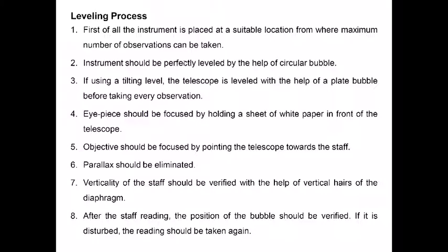Once that is done, you will use the eyepiece to focus on the leveling staff. Focusing is important because that eliminates the parallax, which is the blurriness in your image, or the image is not unique. You get to see two different images, so we have different sorts of errors in the image, and one of them is parallax, and you can remove them by using those focusing screws.